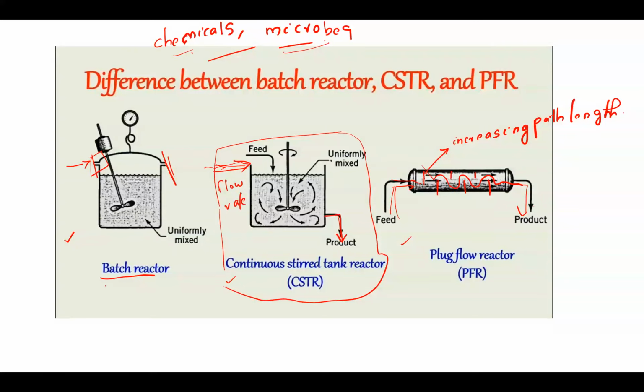Plug flow also, in plug flow we can add in the continuous mode also. Mainly we have seen a lot of continuous mode of operation. So we can continuously feed the liquid, and the byproduct we can simultaneously collect it. But here the mixing is not full mixing. And also here the baffles we are providing to increase the path length, so it gets more time to process.